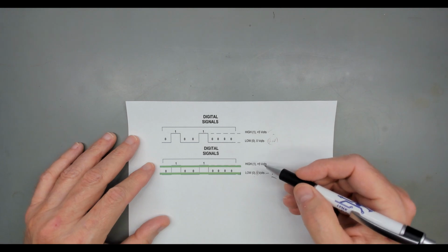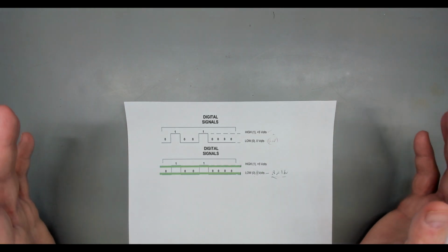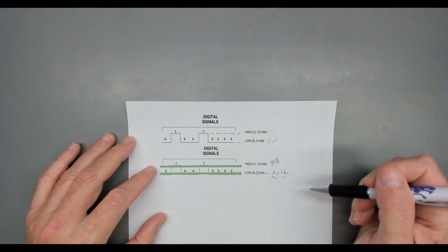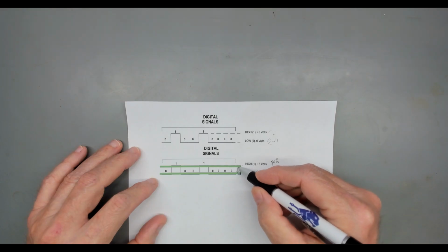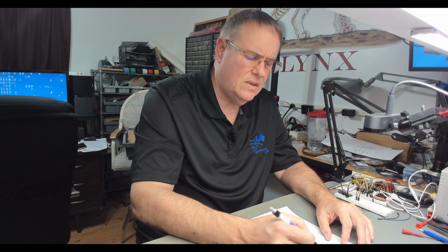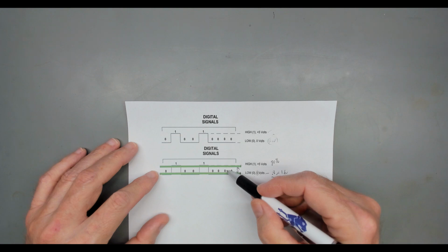On the other end, a high or 1 is also a range. Typically, rough rule of thumb is about 80% of your supply voltage. This means that you've got some range of places where you're 0 and 1. But notice that in here, it appears that you're neither. So that doesn't make a lot of sense. If I'm down here and I'm 0 and I start moving up, what do you mean that I'm nothing here? Well, that's not true. You're not nothing. You just don't change in that range.